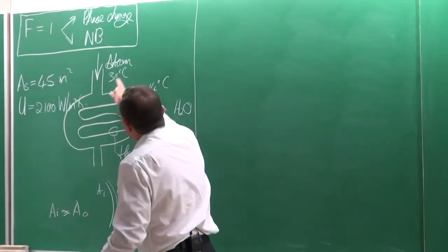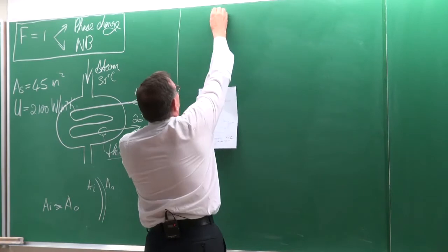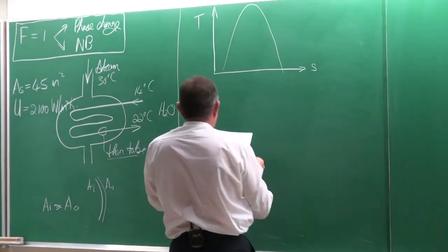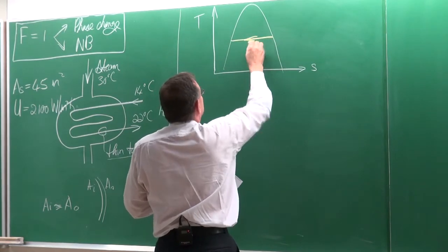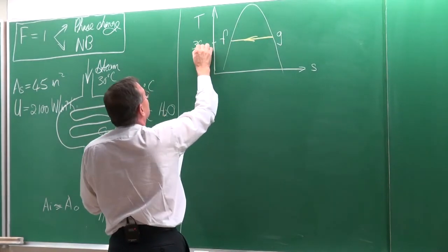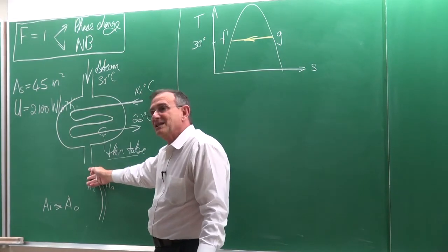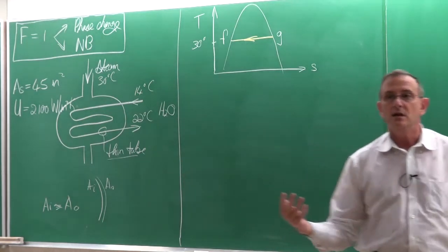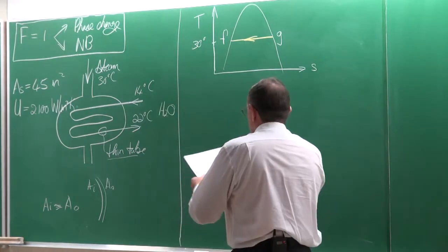Students also have a problem with this. If they look at this, they say in the exams that, oh, I forgot to give the outlet temperature. This is again something that you need to understand. If you look at the TS diagram, if you've got steam at 30 degrees Celsius, then that is saturated vapor, saturated fluid, and that would be 30 degrees. If the inlet temperature of the steam is 30, then the outlet temperature will also be 30, except if more information is given, such as it is subcooled with 10 degrees or 5 degrees or something like that. But no information like that has been given. It therefore means that you now know that that temperature is equal to 30.